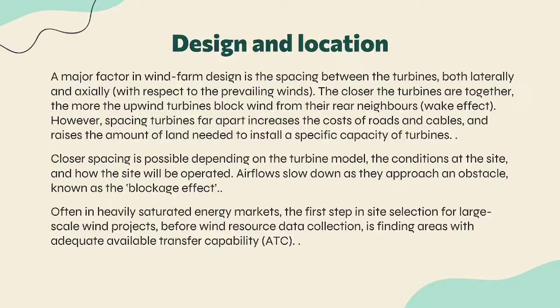As a result of these factors, turbine spacing varies by site. Generally speaking, manufacturers require a minimum of 3.5 times the turbine's rotor diameter of clear space between each adjacent turbine's respective spatial envelope, reducing available wind power by 2% for the turbines in front of other turbines.